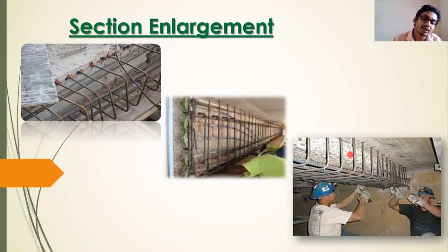If you don't do undercut, you cannot clean the rust on the entire surface of the steel very nicely. And there are even stains on the concrete as well. So the preparation of the surface and all those things is very, very important for getting quality repair work.